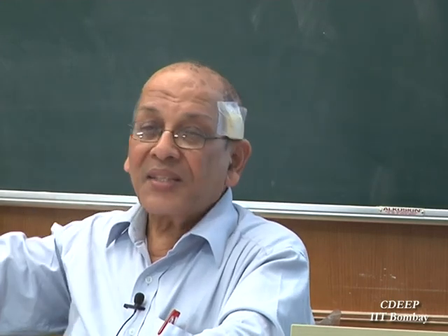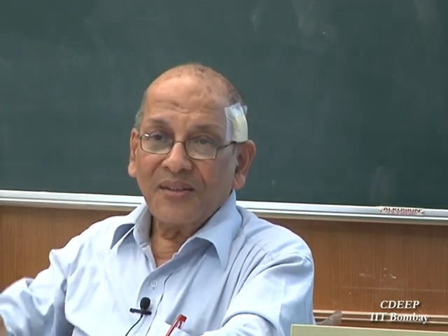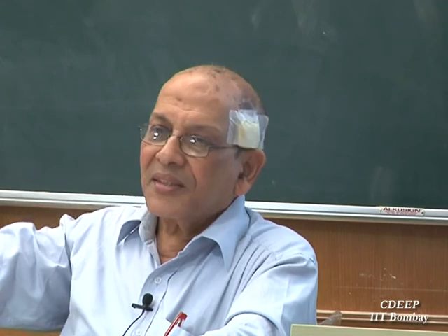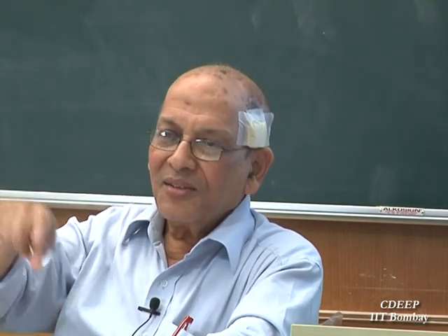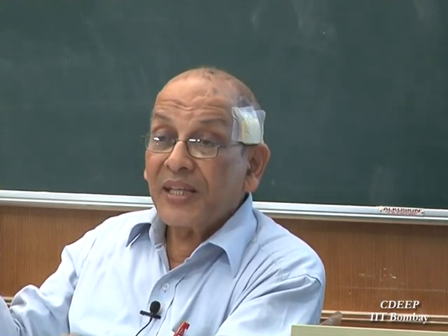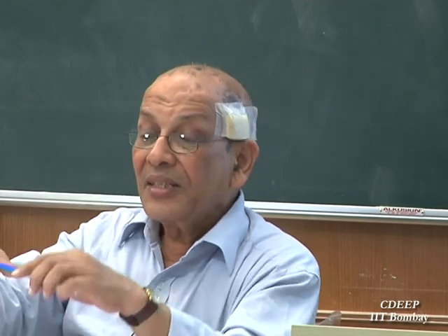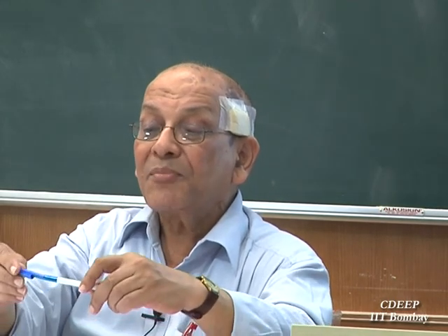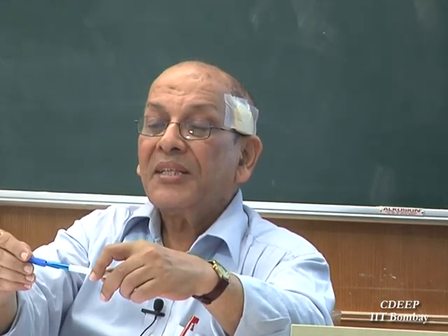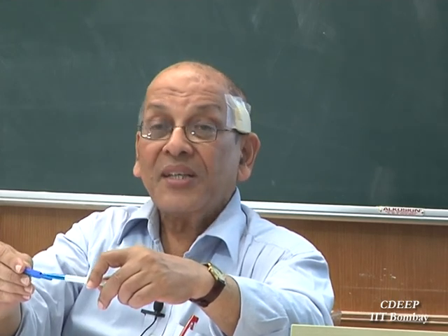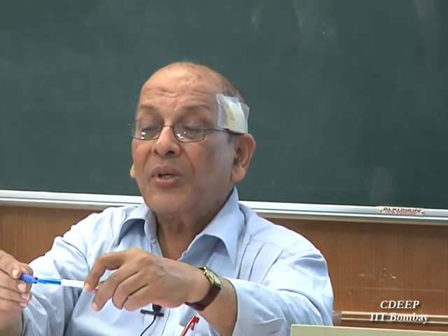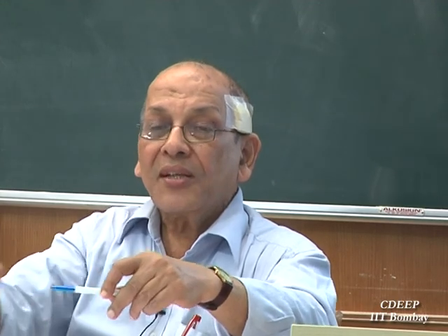So what kind of stress diagram will you get? Rectangular. Top rectangle and bottom rectangle, and stress will be constant, sigma y and sigma y. The entire cross section has become plastic. When the entire cross section becomes plastic, what will happen to the beam? Let us say it starts bending. Ultimately it will become like this. At the center, see, it started like this. So far it was elastic, so it was having some elastic curve. But the moment it becomes fully plastic, it will become two pieces, one here and one here.